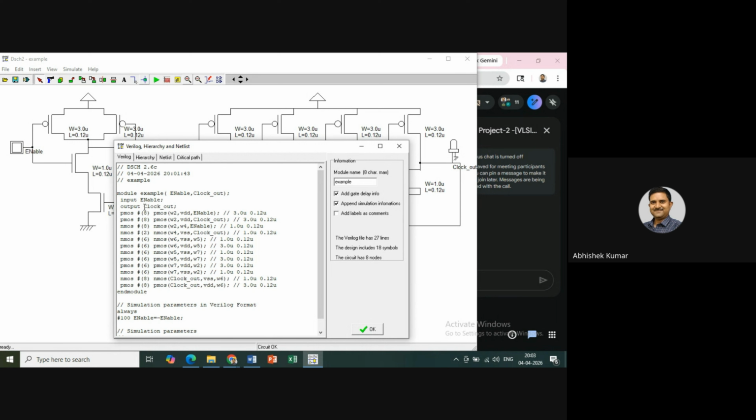So call the NMOS and PMOS from the library and provide the output, input, and enable, which is my control. Here three inputs go to the one transistor. That is my drain, here we have the source, and here my clock is the gate terminal. We can change this value. If I change 3 to 0.2 or 0.1, the delay will be different. So delay depends on the width of the transistor.